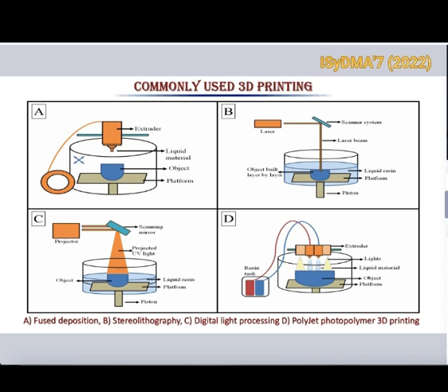The method of deposition of polymer by fusion is a widely preferred process due to its advantage of being inexpensive and easy to use with polymer compositions containing both thermoplastic polymers and also solid particles which are formed. Stereolithography is a low-cost, short-cycle, and high-precision process to manufacture complex shaped structures. When this method is applied in the presence of a light projector, it simultaneously exposes the entire layer to UV light, and this process is called digital light processing.